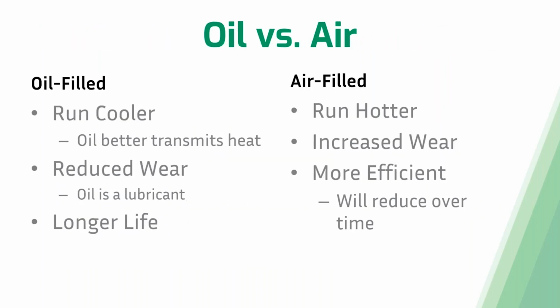So continuing on, let's talk about oil versus air-filled motors. You may have heard of air-filled motors before, and we have decided that oil-filled motors are better. And here's the reasons why. Oil-filled motors tend to run cooler than air-filled motors, and that's because oil is just better at transmitting heat than air is. That's why oil is used in a lot of different mechanical devices. Another thing is reduced wear. Oil is a lubricant, and because of that, the components inside of that pump remain lubricated from that oil, which can help increase longevity of that pump.